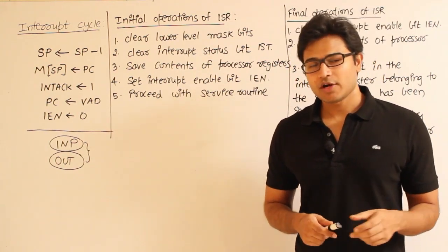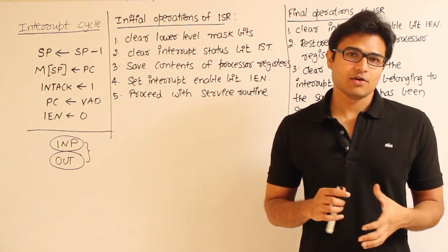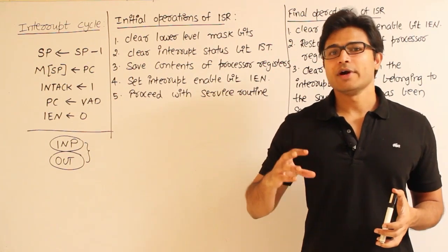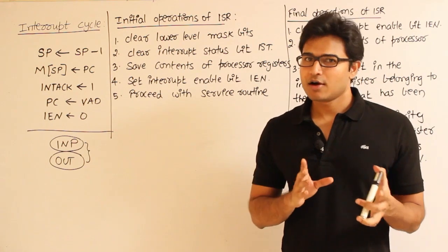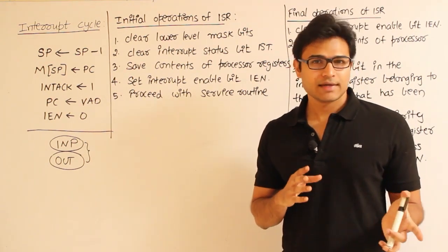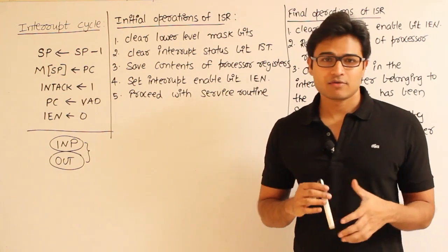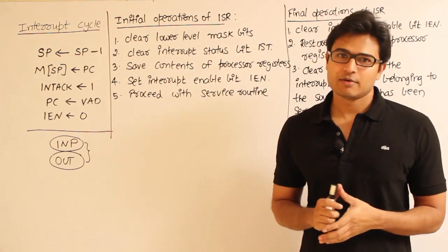So what happens because of the interrupt is most of the things, like finding out who has raised the interrupt and then deciding who has to be serviced first, that is priority, everything is done by hardware. So you need not consider it as overhead because you are not wasting any time. Hardware is fast, and while you are executing something else, everything will be provided by the hardware.